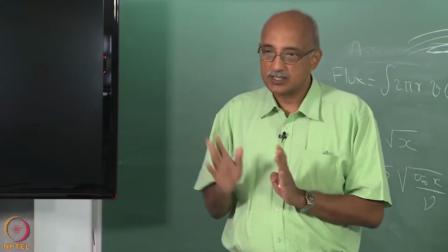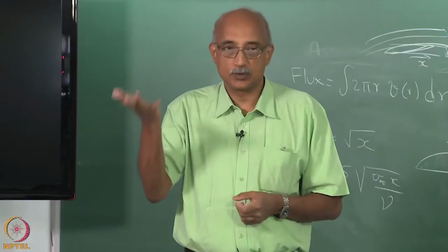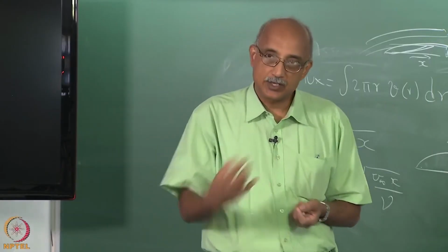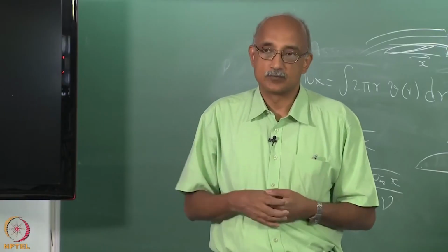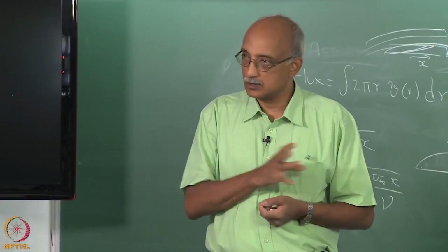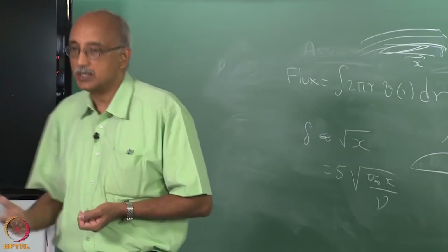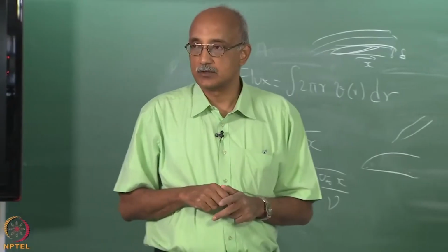So, there is something called Stefan flow, which we will talk about a little later in this course, which is the convective flow that is induced by diffusional flow. Because according to mass conservation, if you have a diffusional flow from the bulk of the fluid towards the substrate, it must be opposed by something. So, the diffusional flow actually induces an equal and opposing convective flow of the fluid, which is called Stefan flow, which can have a very significant influence on the flow dynamics in the system. That is a very important effect in a CVD reactor, which is typically neglected in most of the commercial CFD codes that deal with CVD reactors.